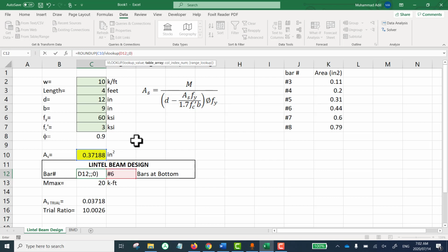With a semicolon, it is asking us, let me close the parentheses already here and then start working inside it. This value is the value we want to look up. Semicolon, in which table do we want to look up this value in the first column? In this table, I want to look up in the first column the value selected in the drop down from here. Then with a semicolon, I need to put two more things in it.